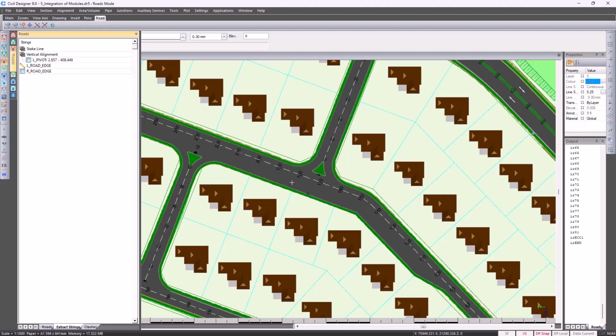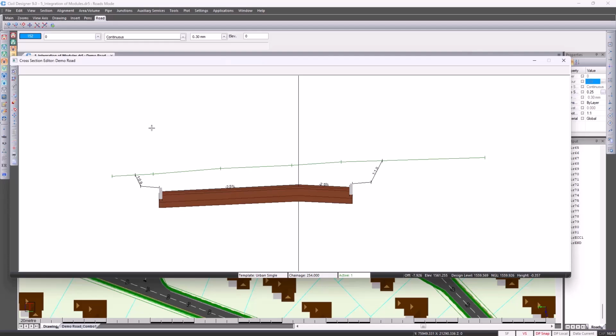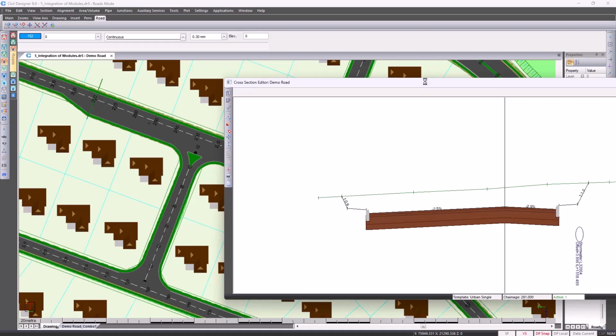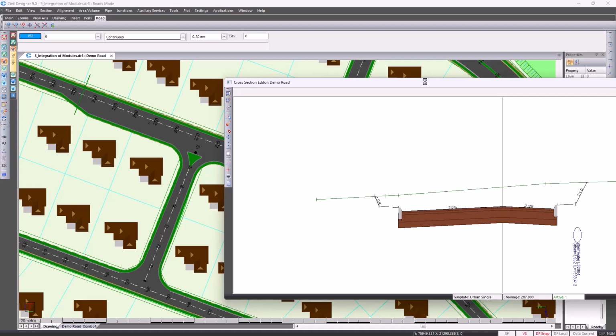As can be seen, the junction is updated. If we go to Section Graphical Edit and we view the new width of our road, there's the additional width. And then pressing page down, you'll see how the width reverts back to what it was, it's utilizing the previously specified grade.